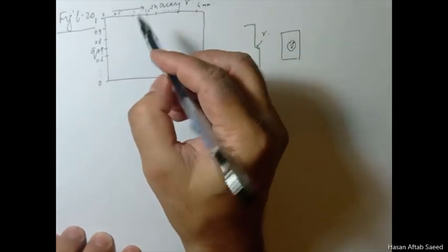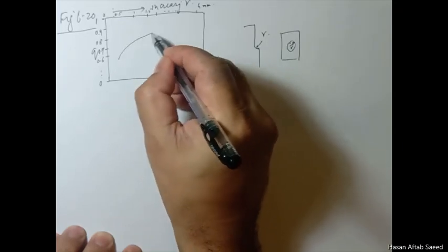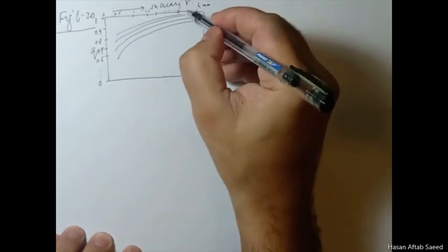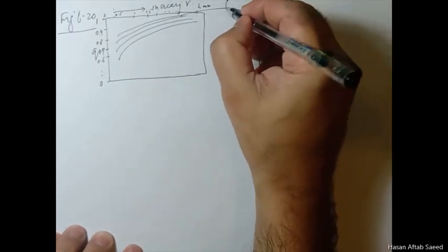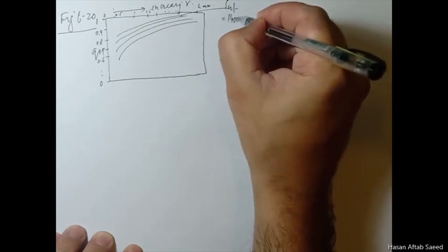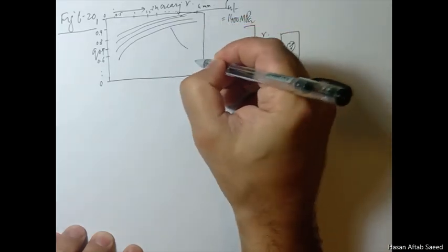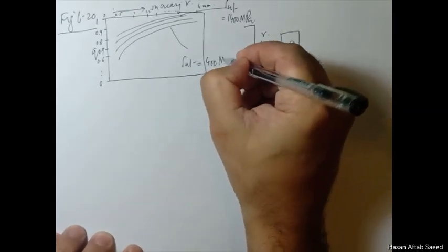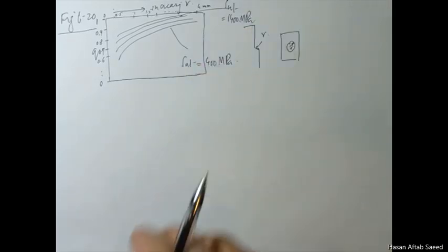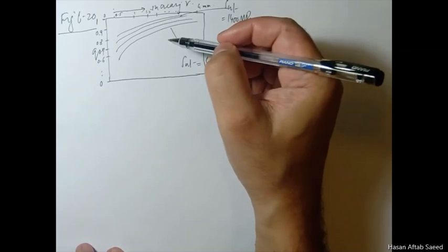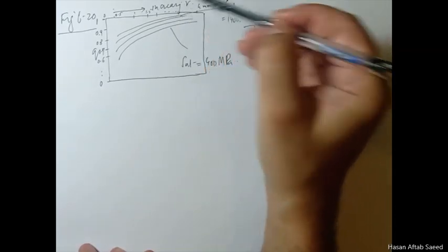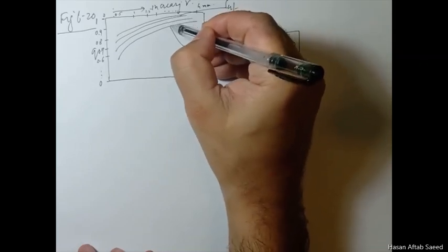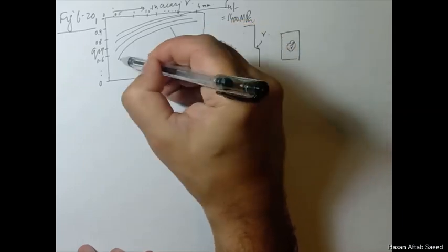Now here you have lines. For example, this line is for steel with ultimate tensile strength of 1400 MPa. This line is for SUT of, let's say, 400 MPa. Now it's easy to discuss this. The materials with lower strengths are the softer steels, with more ductility here.